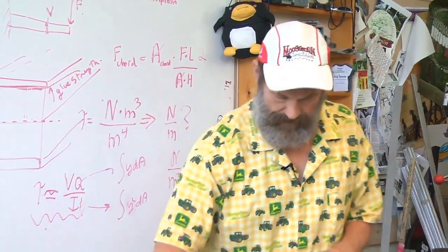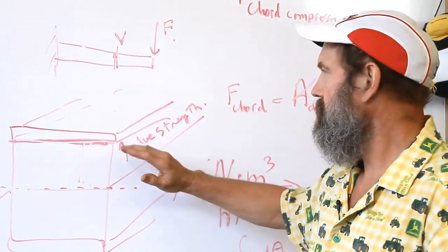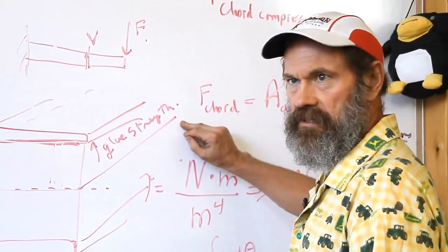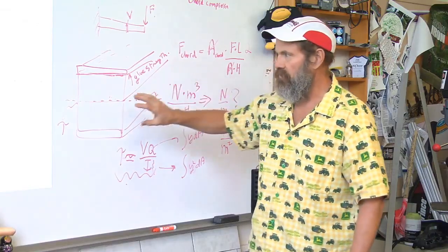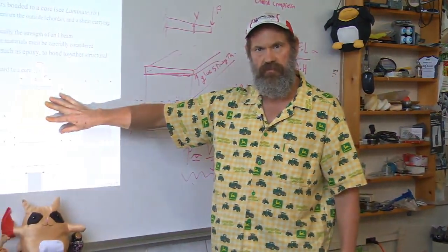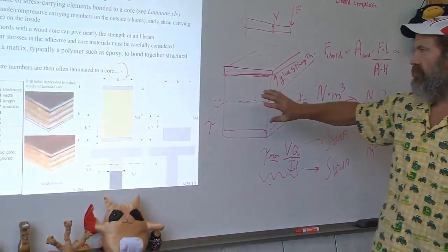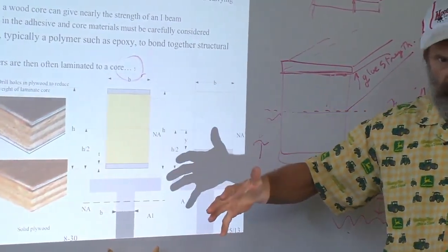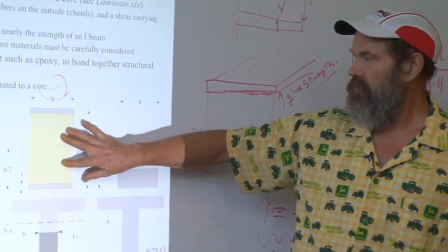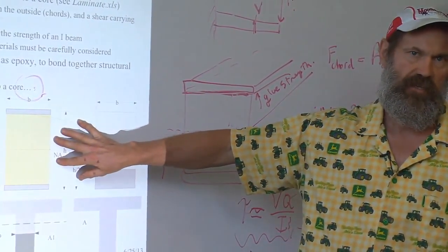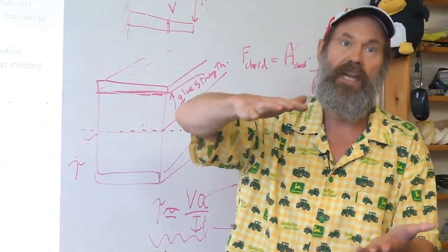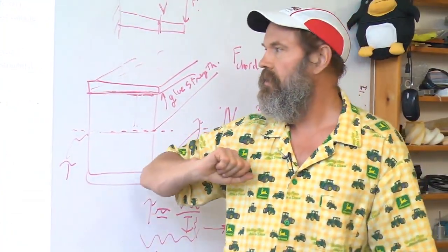You can always check. So now that we can calculate the shear stress in the neutral axis, which is very important if you're using, for example, a soft foam. And you can use rigid foam, but it's foam, so it'll break suddenly. So this would be like the pink insulation foam you'll see often used to insulate. You can actually glue wood to either side of it and make a really stiff structure.